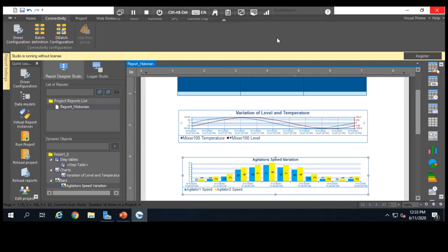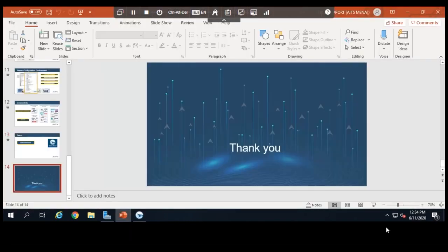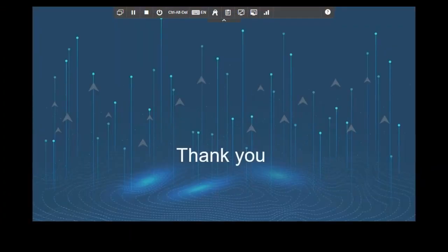Great. Another one here, please. Can I make a template report that can be generated automatically in the Historian Client add-in? Yes, a report template is possible to make. You have the option to save your report as a template, and not only that, as mentioned by Yara, there's a possibility in Dream Report to create also an automatic report in AVEVA's Historian Client add-in.